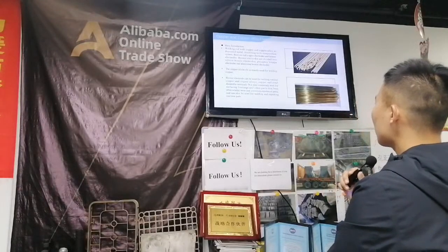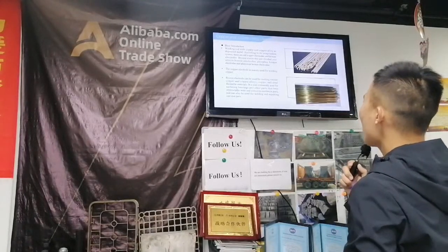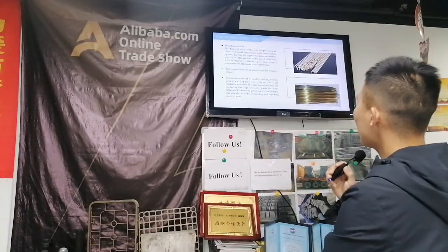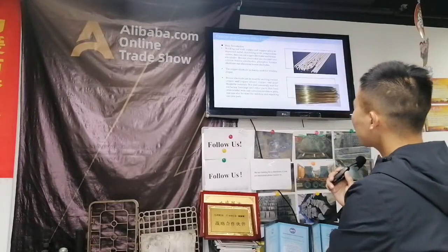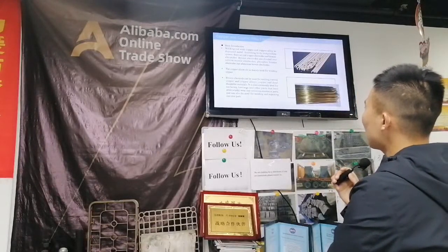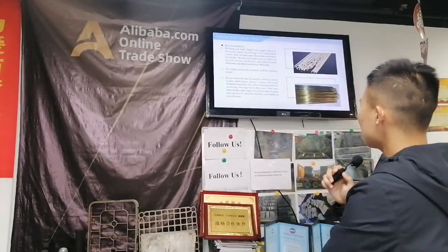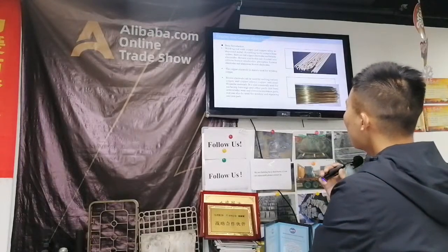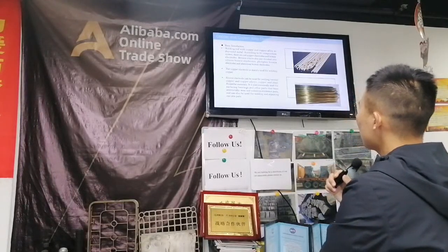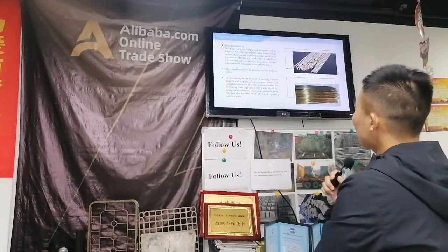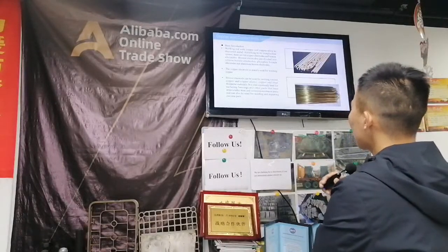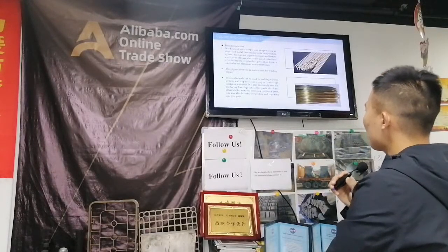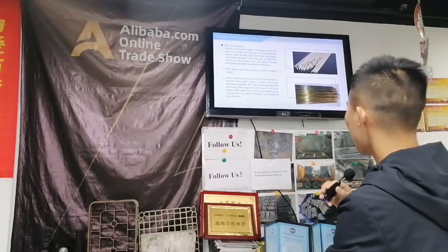The copper electrode is mainly used for welding copper. Bronze electrode can be used for welding various copper and copper alloys, and copper and steel dissimilar materials. It's also commonly used for surfacing rings and other parts that bear metallic wear and corrosion-resistant parts, and can also be used for welding and repairing cast iron parts.